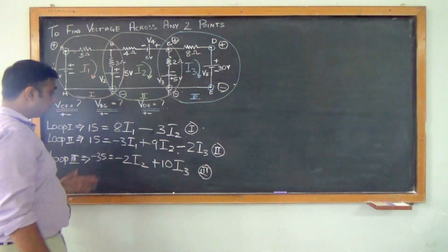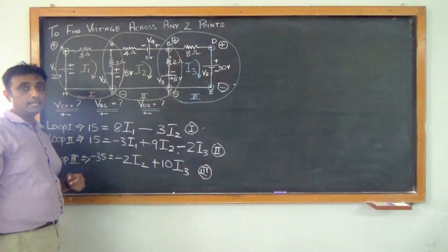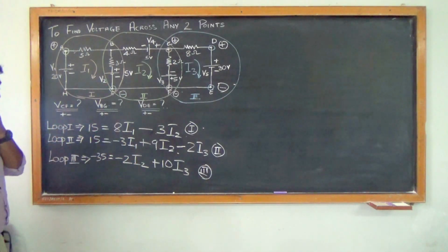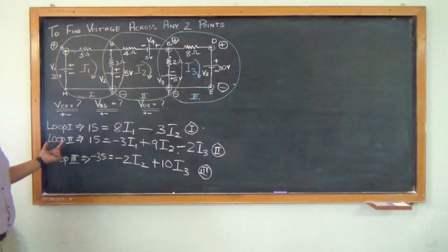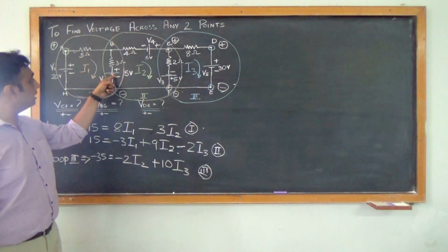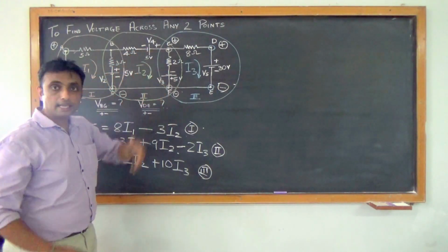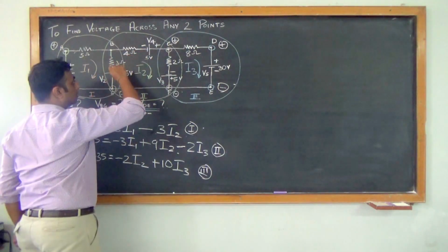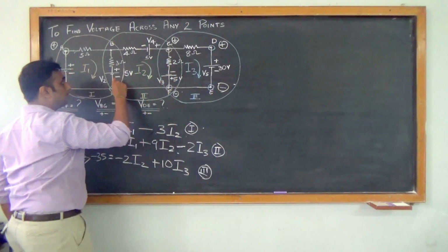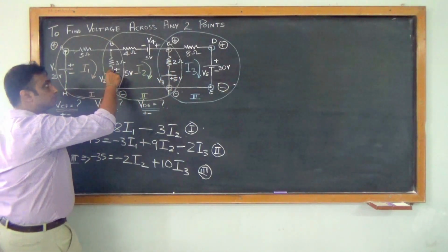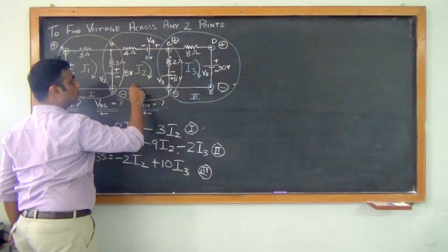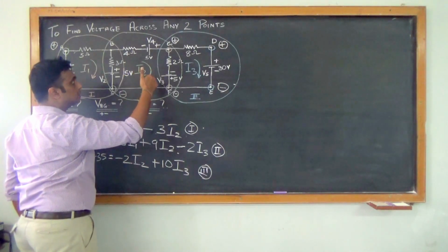The systematic breakup of this is basically already explained to you in the previous episode. But just going briefly, now if I am applying the KVL in loop 2, how many voltage sources are there? 5 volts, 5 volts and 5 volts. Again, current moves from positive to negative if I am taking this voltage source of V2. What is the direction? Clockwise. Matching with this, so it is positive.